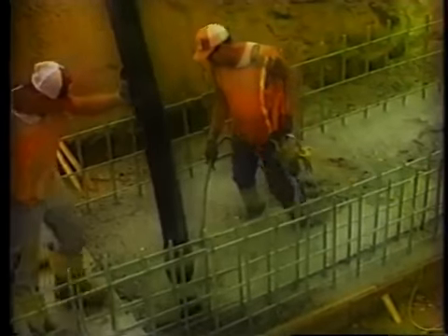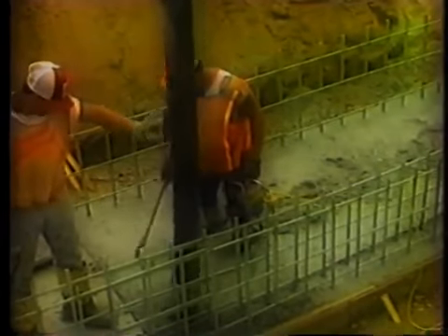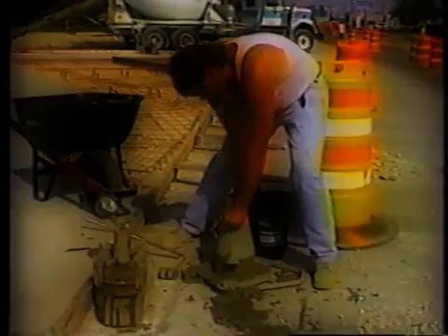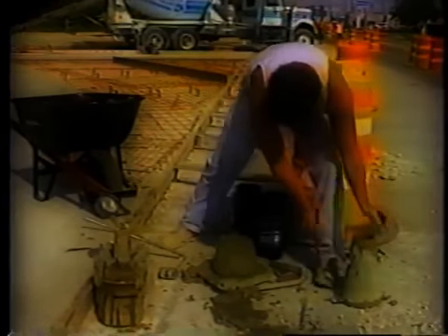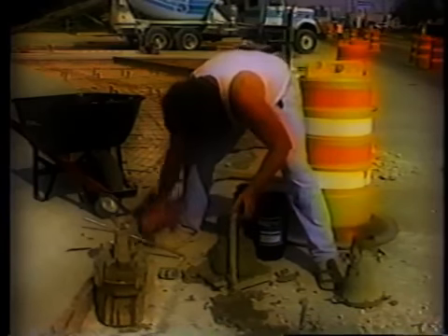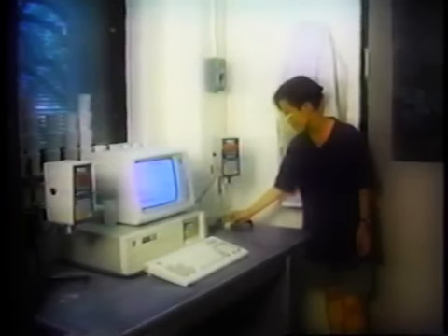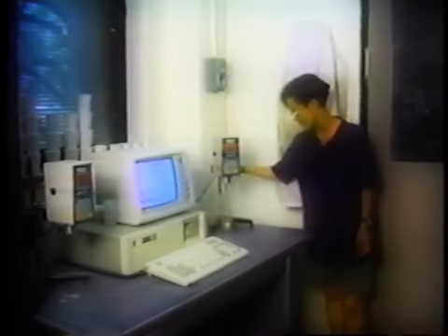The fluid properties of concrete are very important in the field because quality construction demands adequate consolidation. The standard slump test provides a coarse measure of concrete workability. This test is widely utilized because it is easy to conduct in the field. Fluid properties are also the subject of research in the lab because the flow of cement changes as hydration proceeds. Properties such as viscosity and the initial resistance to flow are used to characterize liquid materials.